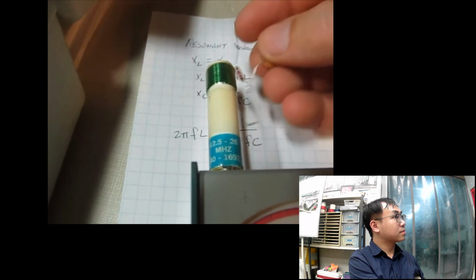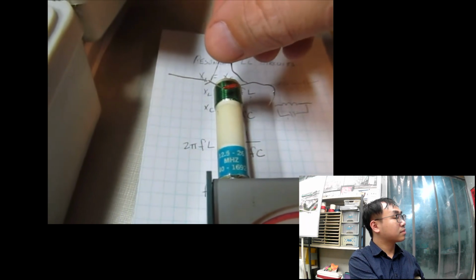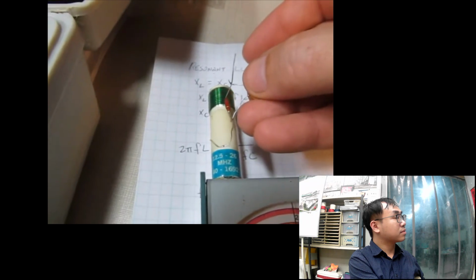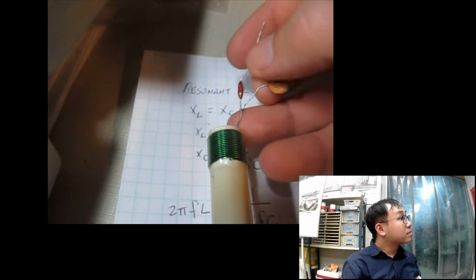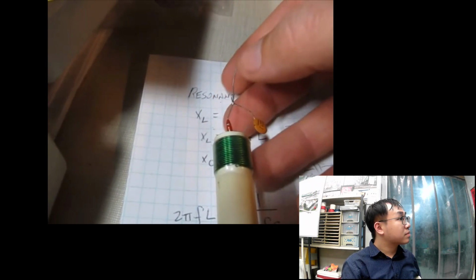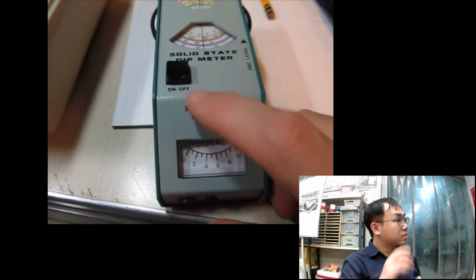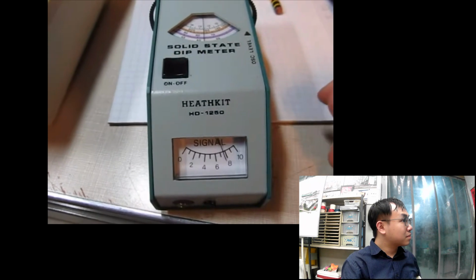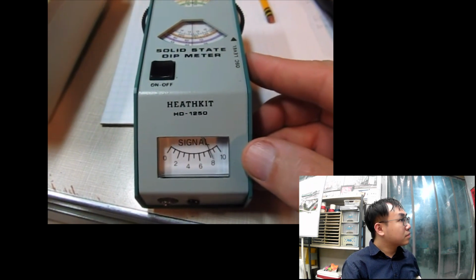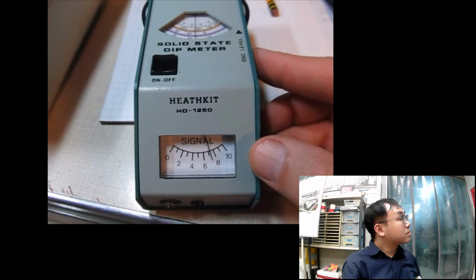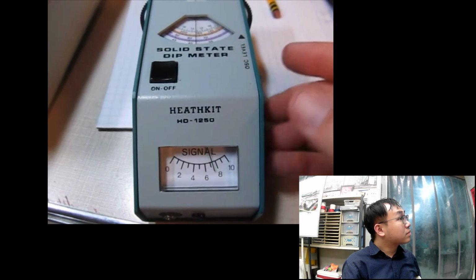Now what we want to do is couple these inductors together. So you don't want to go crossways. You want the coils to be parallel to each other, either like this or in line. What I did is I put a little J hook on the end of this coil so I can stick it right into the coil here, so that it works with one hand. So what we'll do is turn the meter on, and we're going to adjust the oscillation level to a reasonable value. Let's give us about 70% here.